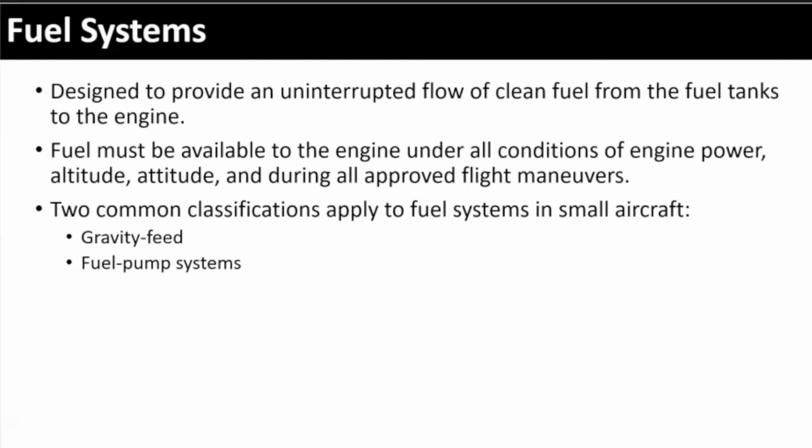You're in a pretty stable attitude in a car, right? Think about an airplane. You want to be really cool. You're banking hard. You're going upside down. You've got to think about the fuel systems needing to operate a little bit differently in an airplane than they do in a car. That airplane's fuel system needs to accommodate those various changes in attitude. The last thing you want is to be banked hard to the left or the right and not have any fuel in the tank on the upwind side. So we need to make sure the aircraft systems facilitate those kinds of attitude changes.